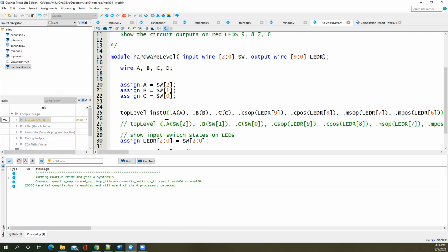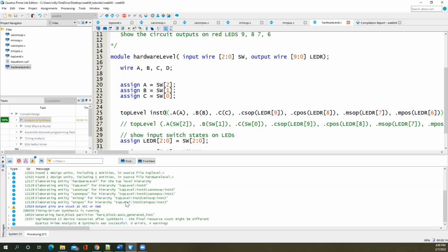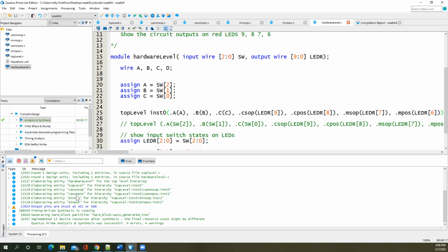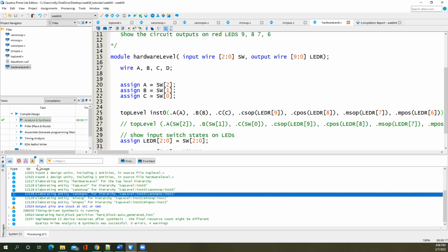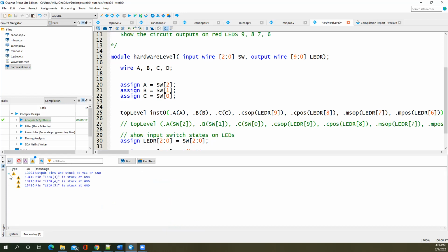Now, there are times when you generate warnings that your design, I'd say works with air quotes around it, but warnings you want to heed, because if you ignore warnings in your code, it will tell you sometimes when you have bad connections, when you haven't connected something. And if you don't pay attention to that and investigate it and decide whether that's something you purposely put in your design and you can live with and record that, or right here, this is what we can live with, but if we had other things coming up, we would want to go correct that.